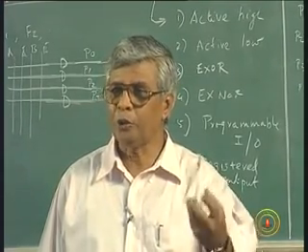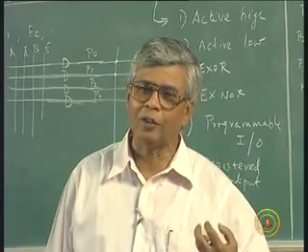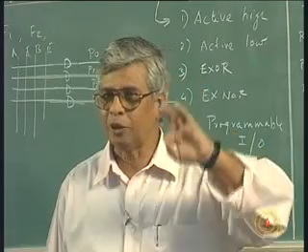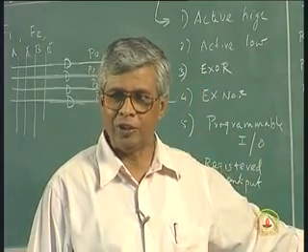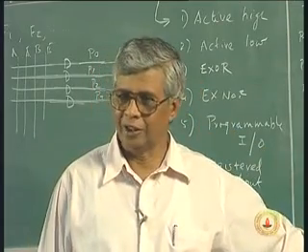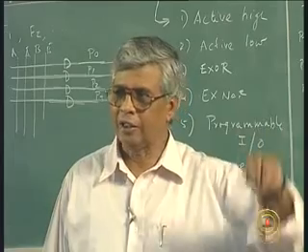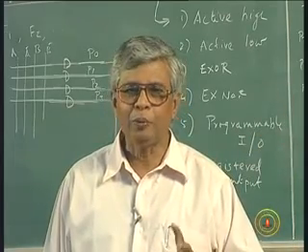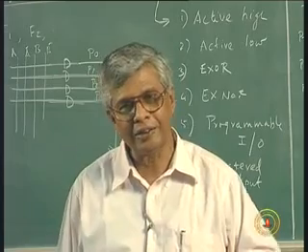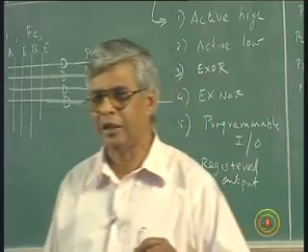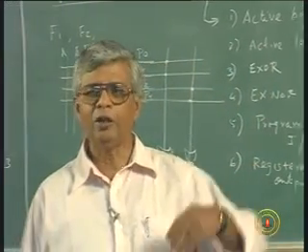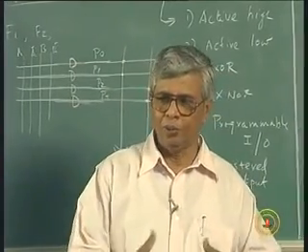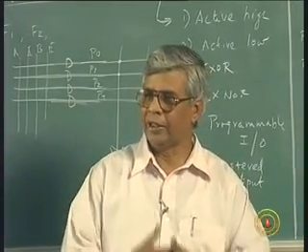So if I can also put that flip-flop as a part of a PAL, I can finish my sequential circuit design in one single chip. Suppose I have a single chip solution for some of the problems we did earlier, sequence detector and all that. We had combinational logic, we had flip-flops outside. Those flip-flops outside need not be put now, because these are small ICs. This is one big IC, or large scale IC or medium scale IC, and you want to have extra small scale ICs, so put together, and again those extra logic, putting them together, wiring, all that come about.